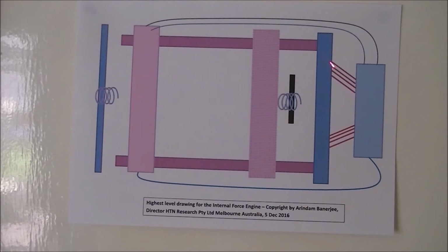So all this current will go to a switching system over here, and there should be two sets of rails for increasing the efficiency. So the switch will, when the power is on, it will be off for the other set of rails. So this depicts that the armature has come from here to here, or it will be going from here to there. So there is only one armature or one set of rails, but there could be two sets of rails to increase the efficiency, because the power is sort of not used in the second stroke, when it is coming back. So we could have another set of rails.